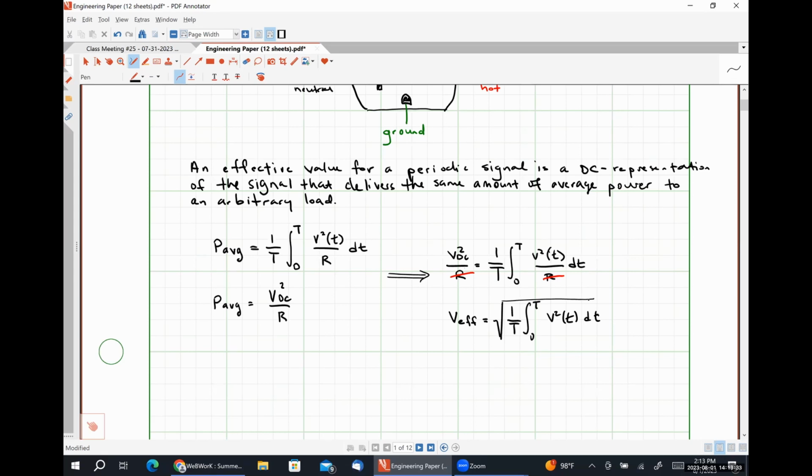So what this mathematical operation is, we're taking the square root, R, of the arithmetic mean or average, so that's M, of the square, S, of the voltage signal. So we get the RMS voltage by carrying out this operation.